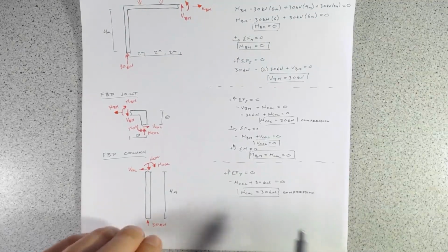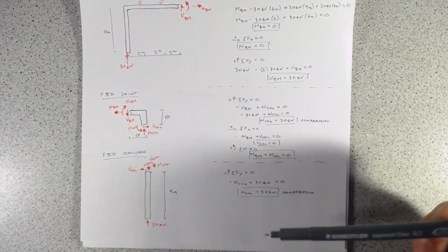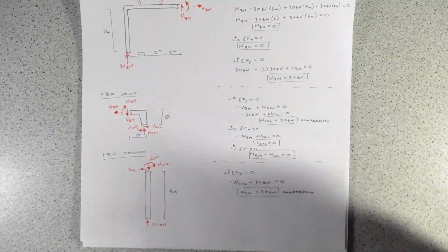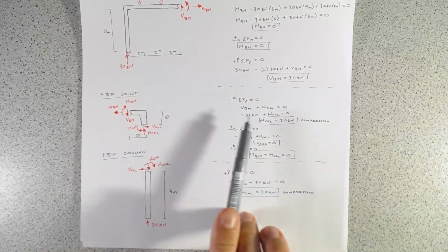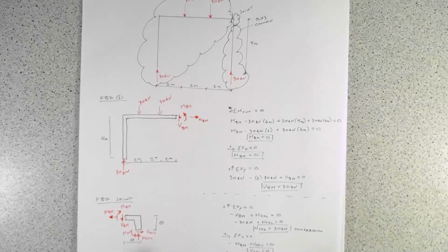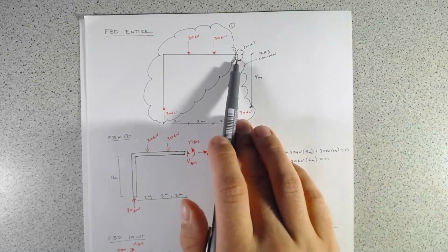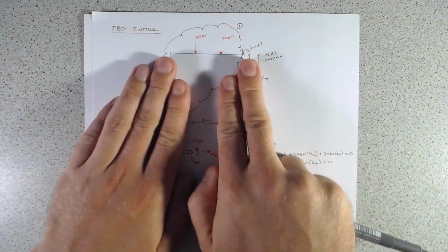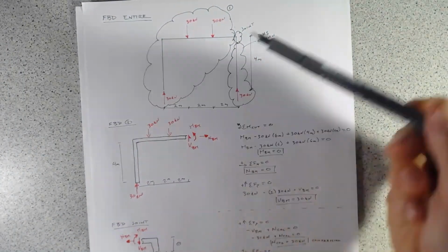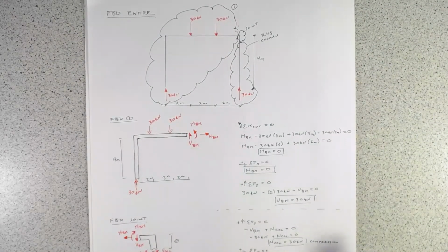So this final check is essentially like a statics check for us. This is what we expect. We're getting it from two different free body diagrams using two different methods. The other thing to keep in mind is that here again, the shear in the beam is becoming the axial load in the column. That makes perfect sense because if this was just a simply supported beam, you'd have two reactions just like you have here. Essentially all we've done is extend those reactions and turn them into columns.